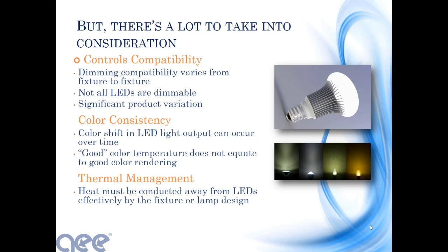And if you think about the same problem you had with CFLs, when CFLs came out, they're the solution to everything. They're going to last forever, okay? That lamp hour rating was based on you screwing it into a lamp where the heat goes up into the room and dissipates great. Okay? What do we have up here? Cans. So what are you doing there? The exact opposite. You're putting the temperature-sensitive device at the top where the heat rises and it's basically an oven.